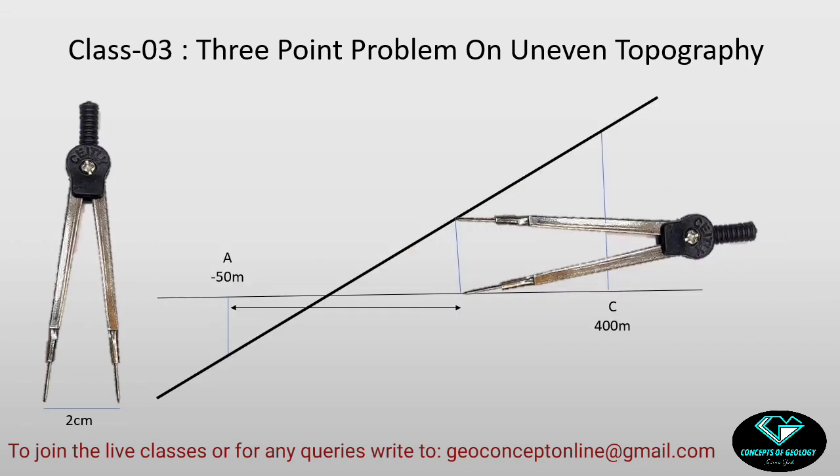Now coming to the previous example, suppose this line is the MSL. I had the borehole point A here, and according to my map scale, suppose this value is minus 50. So it will be in depth with respect to the MSL, the datum plane. After that, I had the C borehole here, and here the RL of the coal seam was positive 400 meter. So it will be at elevation with respect to the MSL. I am drawing the 400 meter line here. Suppose this is 4 centimeter according to my map scale.